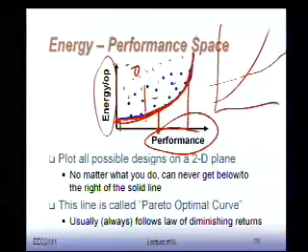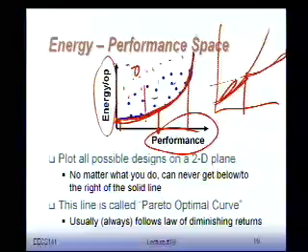So if you look in energy delay space, every adder will have its own optimal energy delay curve. So if I'm sitting and I'm interested really in low performance, you see that the ripple adder is going to be better. If you're at high performance, actually, you're going to be better off with the look-ahead structure. So now by superimposing some of those energy delay curves on top of each other, I can figure out which structure is the best for what performance region.